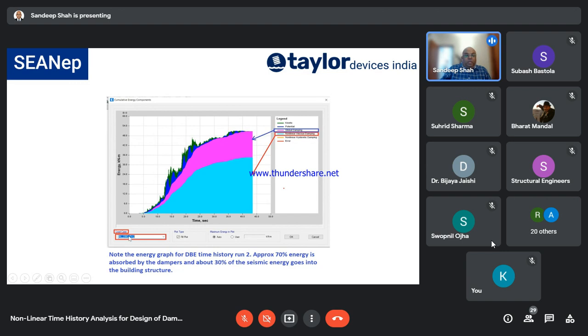Now over here you can choose another DB load case, or you can choose an MC load case. So this is the load case that we have defined. Different load cases, it will keep showing you results. If this is giving you unreasonable kind of values, either showing the blue portion very high or showing the pink portion very high, it means there's something wrong.